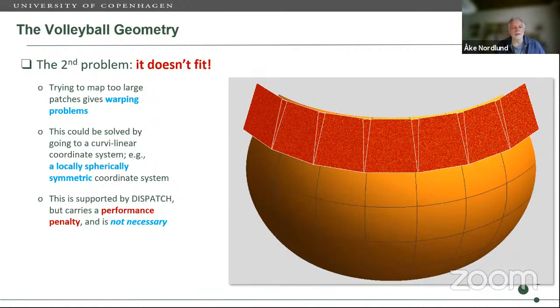And you take that into account, and then you have something which is a representation of a sphere by hundreds of thousands of little boxes that all are Cartesian. And having them Cartesian has a huge advantage compared to using, for example, spherical geometry. Namely, there aren't that many good solvers for spherical geometry. You're bound to then use just a few very specialized ones. But if you have a Cartesian box, you have hundreds of solvers to choose from.